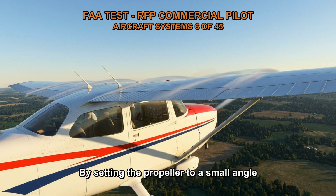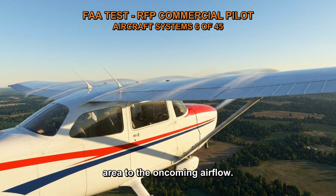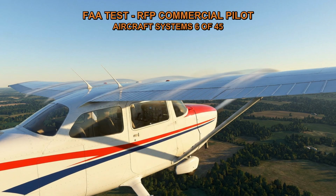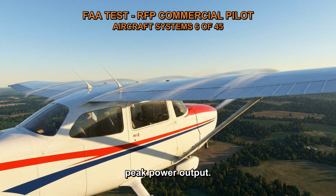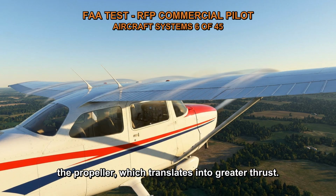By setting the propeller to a small angle of attack, the blades present a smaller surface area to the oncoming airflow. This reduces drag and allows the engine to produce more power, resulting in increased thrust. Additionally, setting the propeller to a high RPM ensures that the engine is operating at its peak power output. This provides the maximum amount of energy to the propeller, which translates into greater thrust.